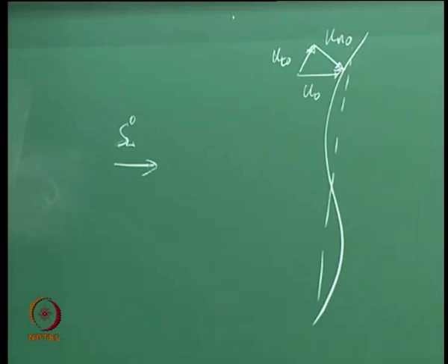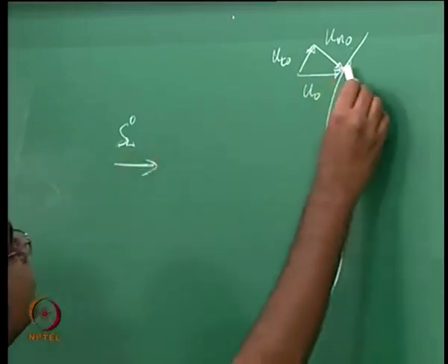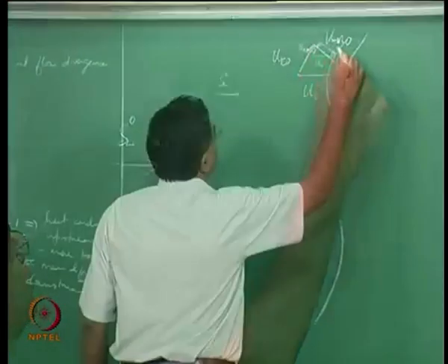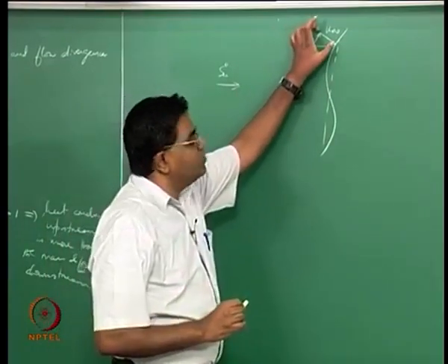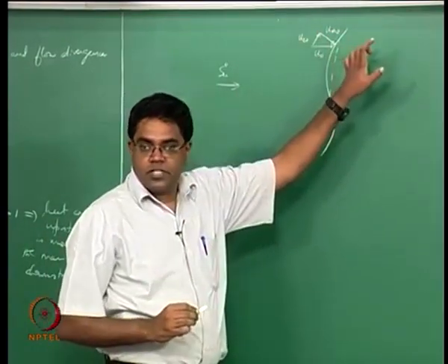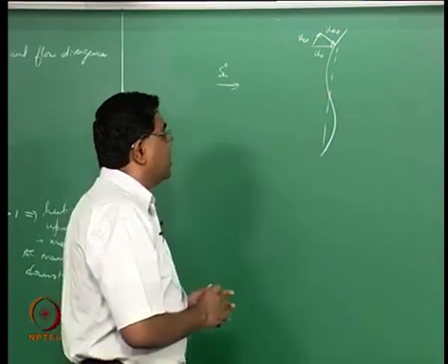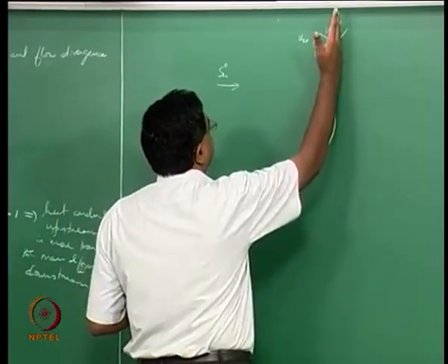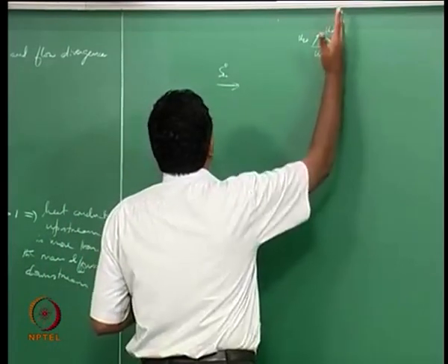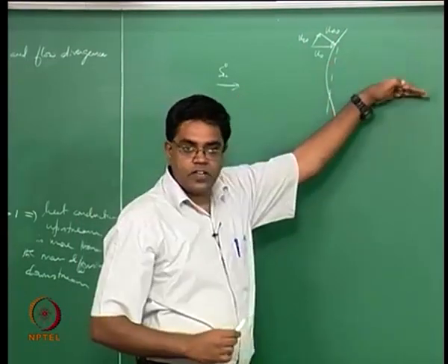And what happens is when you have a flow that is going past the flame, it's mainly the normal component that suffers the expansion, because that's how we are normally thinking about a flame. So if you had an unperturbed flame with a flat profile, then the normal component of the flow is going to actually expand.